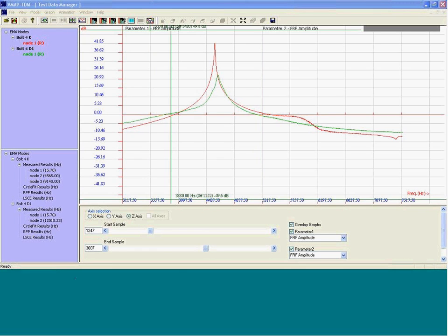Going back to my slides, in summary, we are able to use modal analysis as a technique to classify boards as an application in manufacturing line. And this is enabled because we are able to identify significant differences between resonance frequency and damping. And of course, what's very important is selection of sensors and excitation location, and that will make sure that the defect detection process is successful, and it is critical for this experiment.